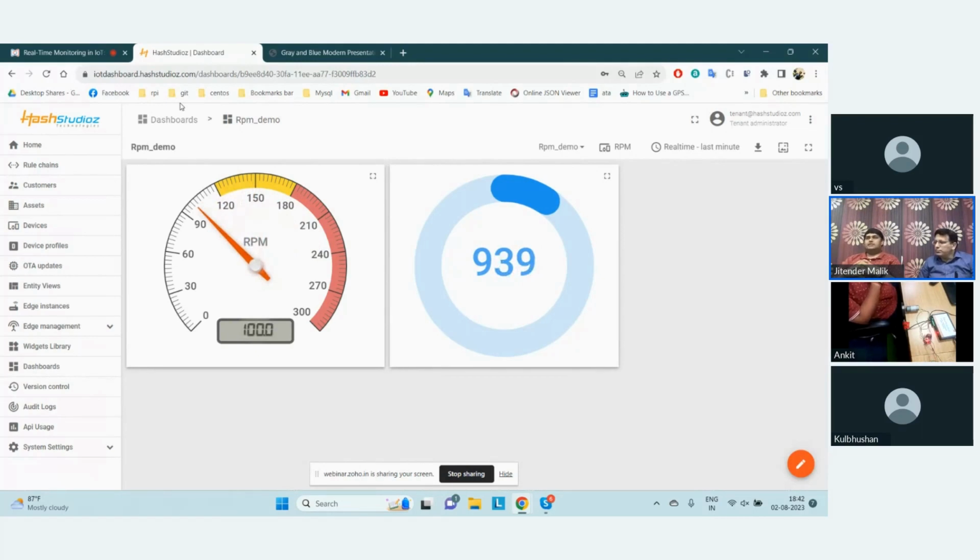This is one of the examples of high-speed data processing where I am counting the pulses, and you can see we have multiple white spots on that wheel, so that we are not restricted to a single pulse in one rotation. We are holding multiple pulses in a rotation, so that we are able to reliably detect the speed.